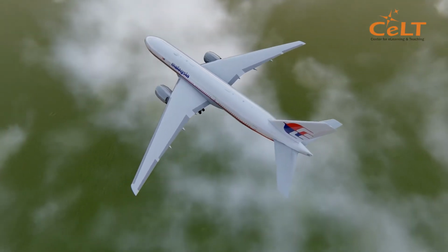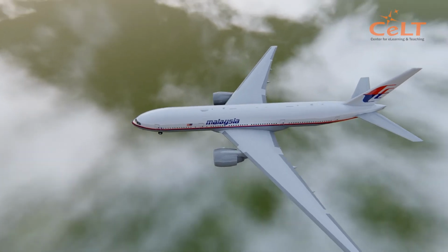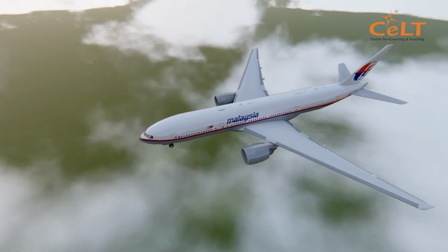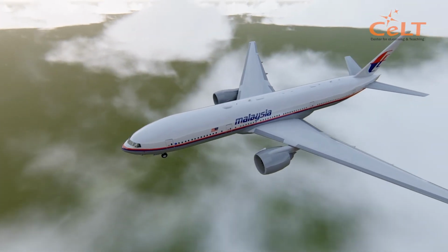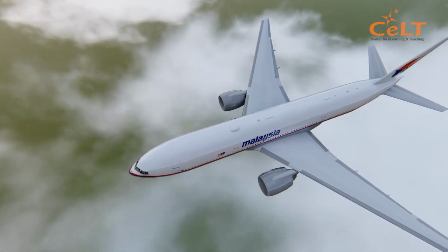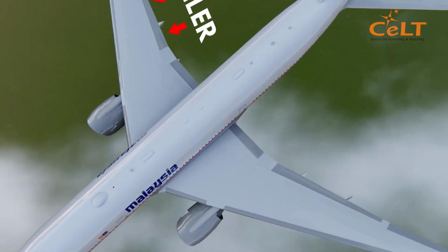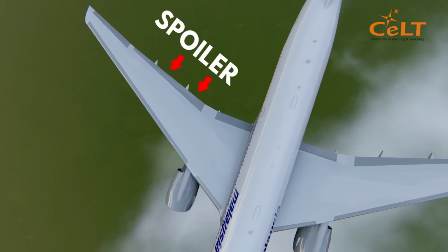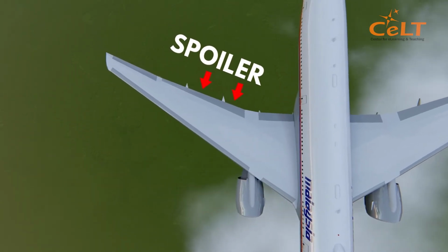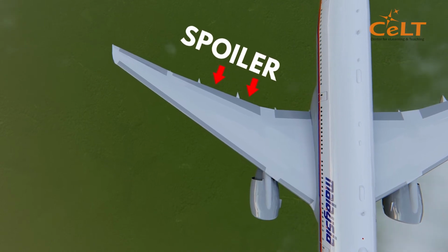Spoilers, located on the upper wing, when open, decrease lift and increase drag. They reduce lift by disrupting the airflow over the top of the wing. They are used during the descent prior to landing and immediately after landing.